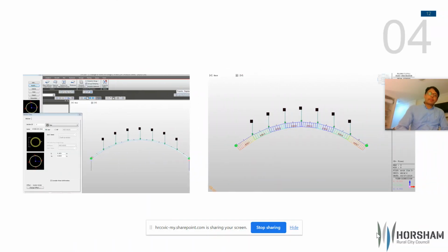So here is some analysis of the CFST Arch Bridge design using MIDAS. In the design of the CFST, as I said, whether it is a 20-meter span or 200-meter span, the processes are the same. The buckling or geometric failure of the structure is the main key. So we did the analysis using the ANSYS software to do the buckling analysis.